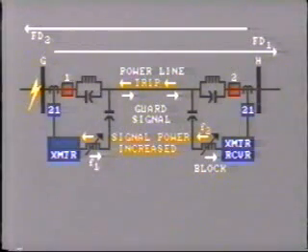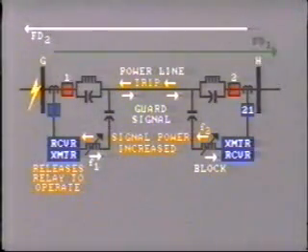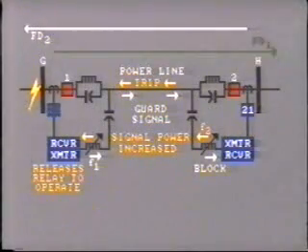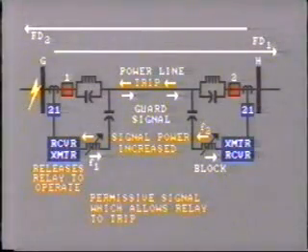When this signal is received at station G, the relay is released to operate. But as we have just mentioned, this relay, FD1, does not register the upstream fault and therefore will not trip. In effect, the transmitted signal is applied as a permissive which allows the relay to trip when the fault is within the protected zone.